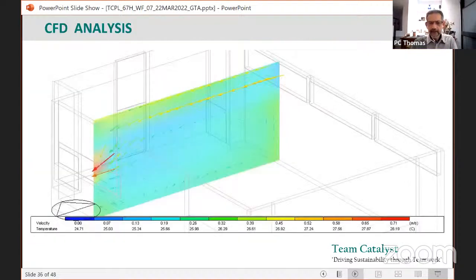Okay. Now, within Design Builder, there is a CFD engine, so you can take an hour and then get it to model what the temperature distribution is within the space. You can't do that in the natural ventilation options I showed you before. That does a bulk airflow every hour. This is for that 1 hour.